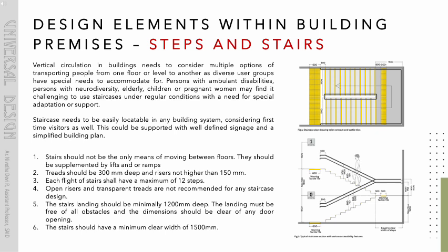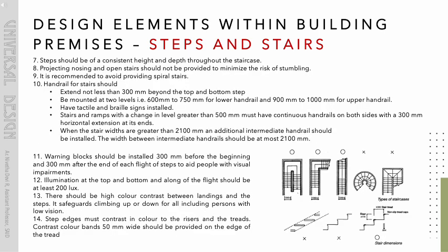The stairs landing should be minimally 1200 mm deep. The landing must be free of all obstacles and the dimensions should be clear of any door opening. The stairs should have a minimum clear width of 1500 mm. Steps should be of a consistent height and depth throughout the staircase. Projecting nosing and open stairs should not be provided to minimize the risk of stumbling. It is recommended to avoid providing spiral stairs.